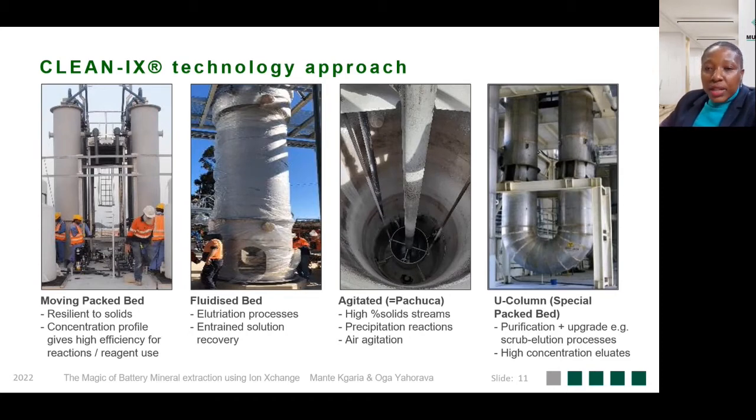Airlifts are used to advance resin in between the vessels. Some of the conventional designs will use eductors and pumps to advance resins through the column. However, this can be detrimental as it can affect the mechanical properties of the resin, resulting in resin losses. So the moving bed is versatile. It can achieve countercurrent movement of solution and resin.